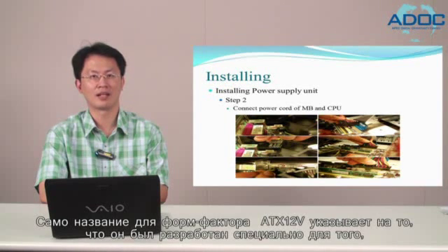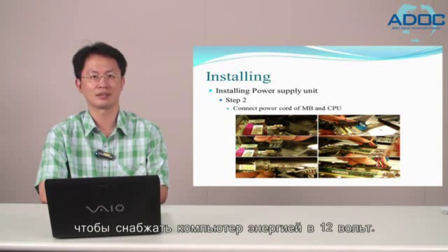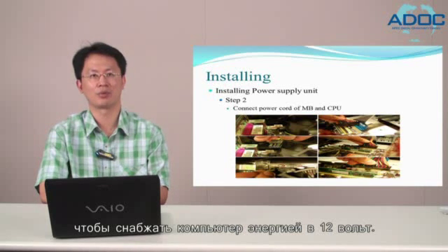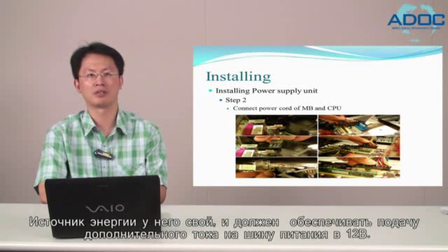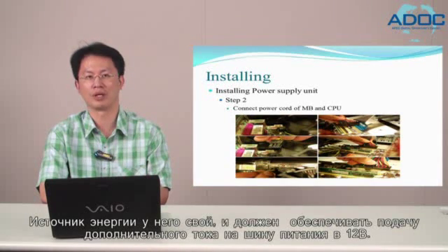The oddly named ATX 12-volt connector is specifically designed to power the processor with a clean 12-volt supply and should be powered from its own 12-volt rail.